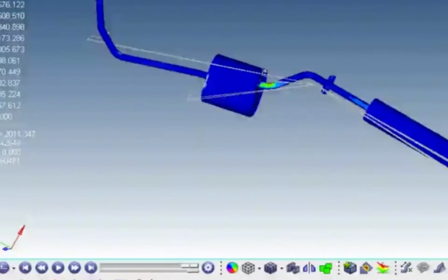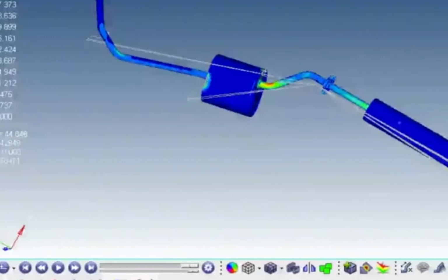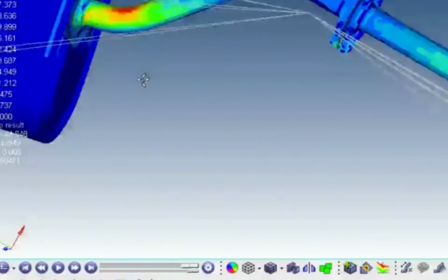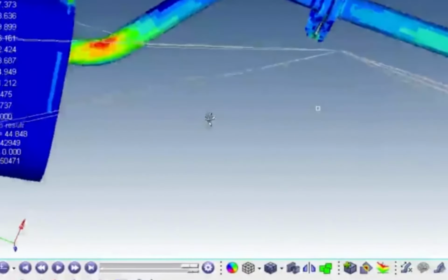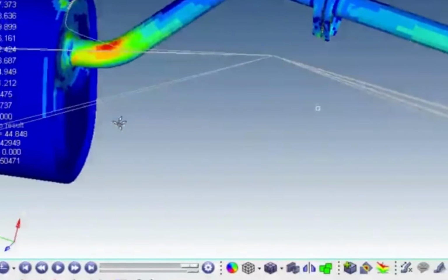Probably the first result that's of interest to you is the RMS stress. If I click on that one, we're seeing 44 megapascals, 45 megapascals RMS stress, I think pretty well at this position here. Let's go and have a look. So it's kind of occurring on the tube. Now, I have no idea whether this model is realistic or how it's behaving, but I'm just using it as a mechanism. And the other thing that isn't done properly with this model is there's been no effort taken to model the welds as welds. So you could do that. We have weld materials, but in this particular case, we've just included them as a standard group. So that's the RMS stress.